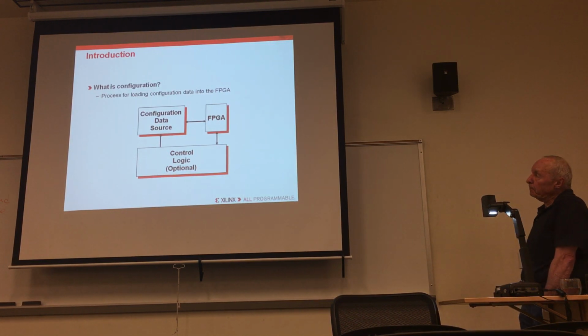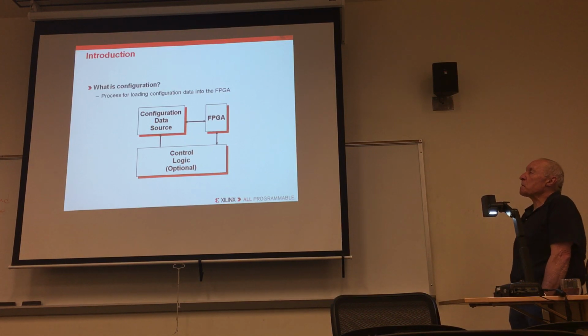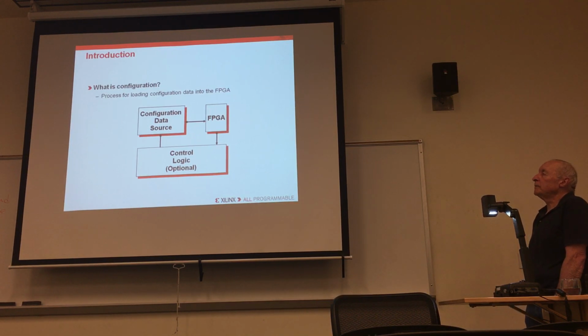Depending on the configuration mode you choose, there are two types of data paths, serial and multi-bit. Serial data paths are used to minimize the number of device pins required. Multi-bit data paths offered include by 8, by 16, and by 32 bit widths. These are used for higher performance or enable access to industry standard interfaces. These multi-bit solutions are ideal for connection to external data sources like processors or parallel flash memories.